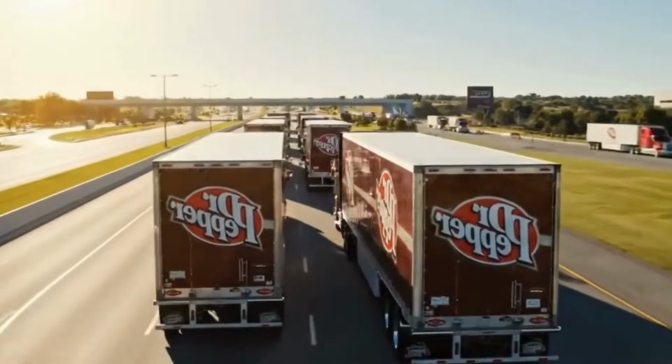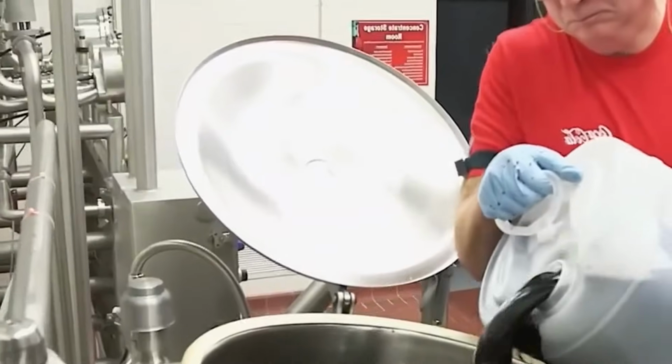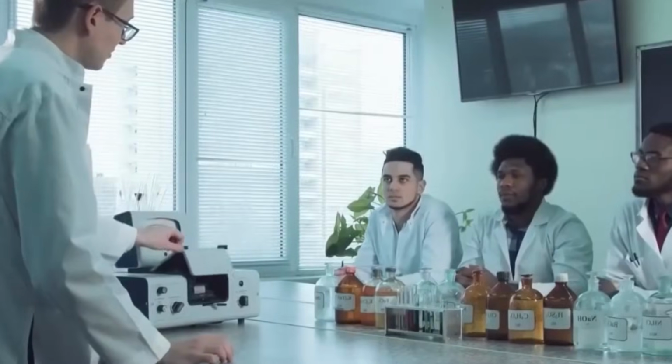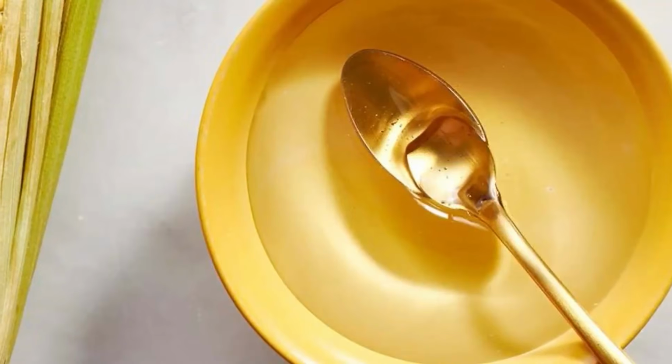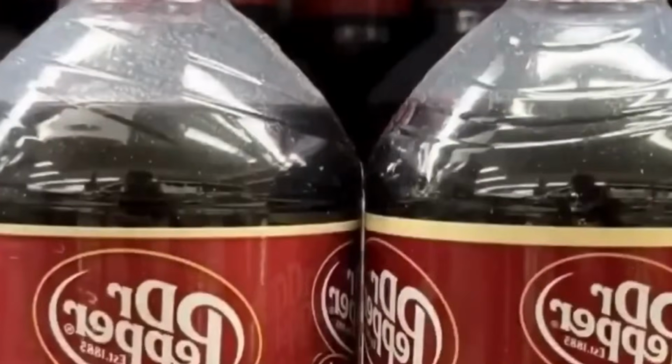The mixture then enters a deaeration chamber where it is subjected to vacuum pressure to remove entrained oxygen and carbon dioxide, which can affect taste and carbonation efficiency. Following deaeration, the liquid enters a carbonator.